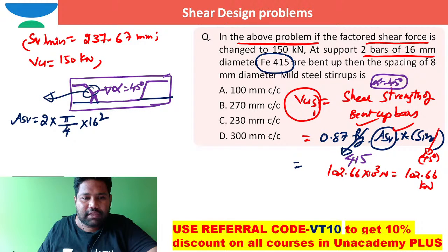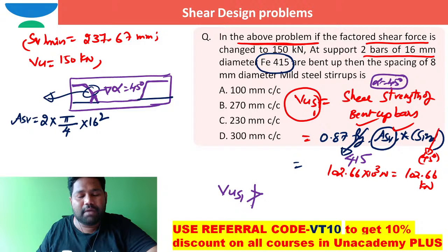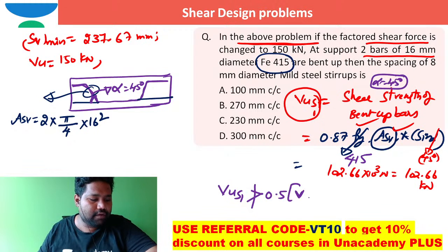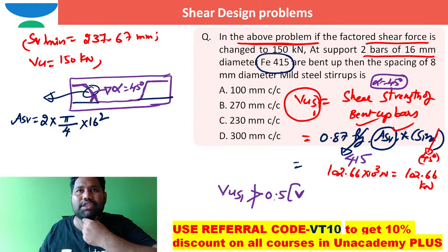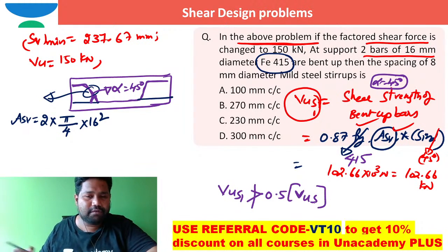The shear strength of bent up bars VUS1 is limited to a maximum of 50 percentage of the shear force to be resisted by shear reinforcement, that is, 0.5 times VUS.